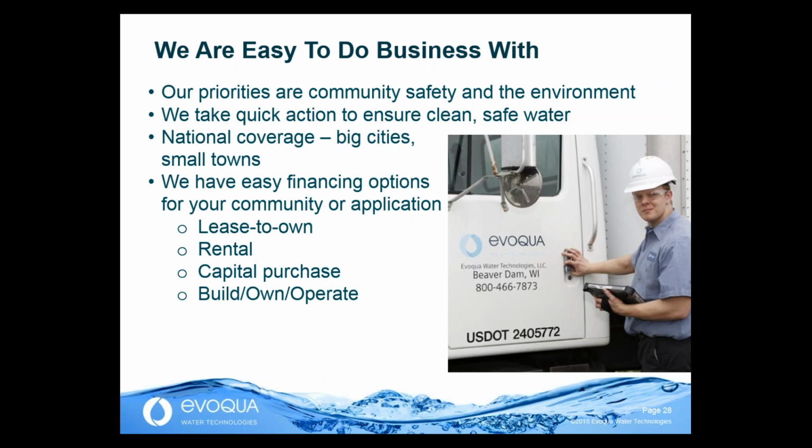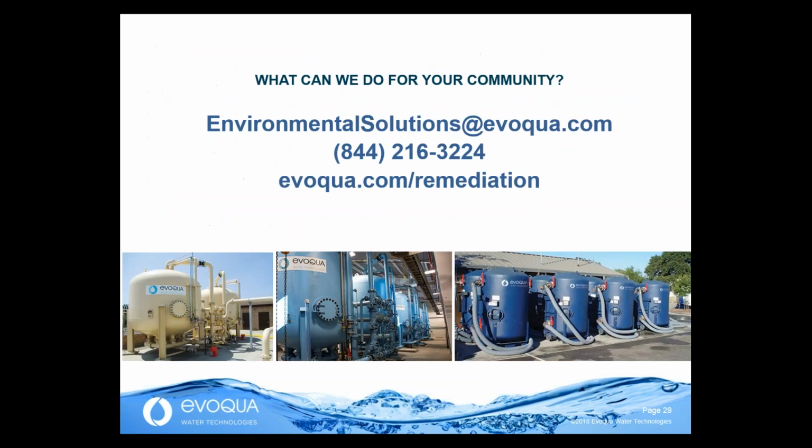Costs vary depending on how you look at them. The first aspect is clearly the capital installation. The capital for carbon is higher because it has much higher empty bed contact time than resin: 2 minutes for resin, 7 to 10 minutes for carbon. As a result, we either need more vessels or larger vessels for carbon, depending on the flows. And what we find is that we have a much smaller footprint with resin, probably half the size, and capital is probably about 2/3 of the cost of carbon.